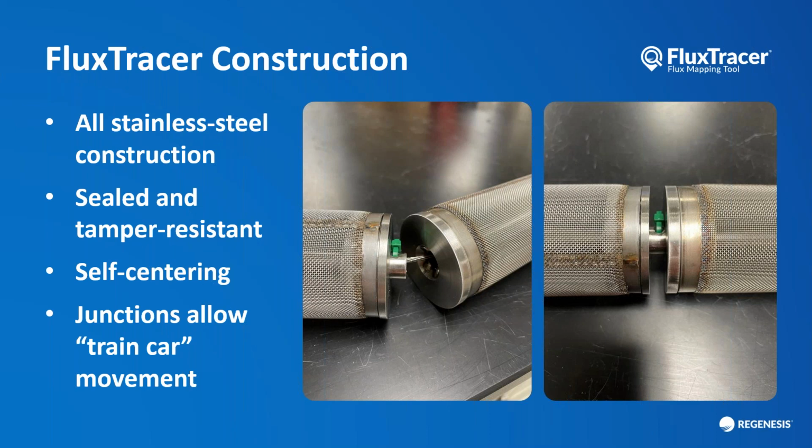So the construction of the canisters took a little bit of work, and what we've settled on is this self-centering design that makes the devices kind of snake down the well easily, and there's low risk of them getting hung up, even if there's a little bit of a deviation in the well. This junction that they have between the canisters allows them to move like train cars, we call it. And in all of our field deployments so far, they've gone quite smoothly, and we expect that to be the case in the future.